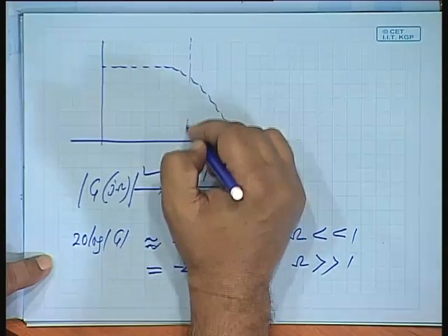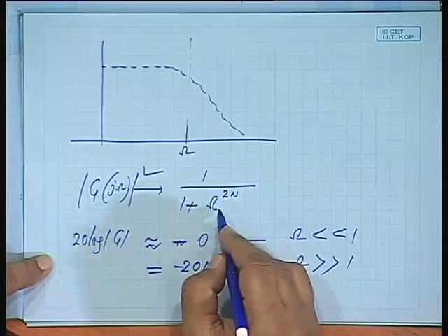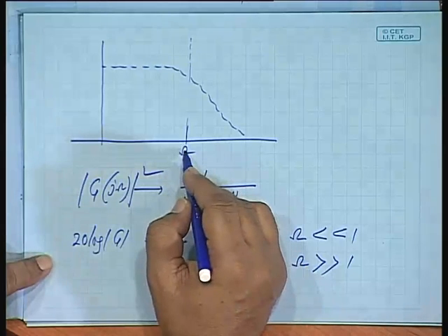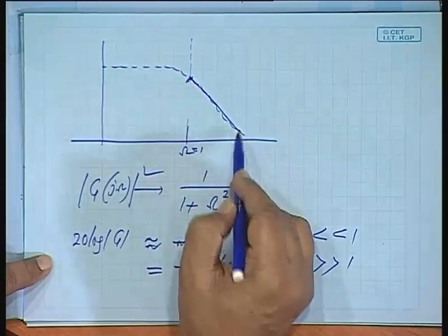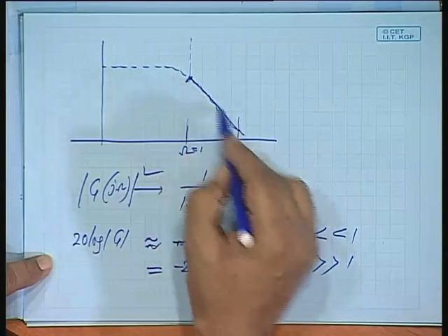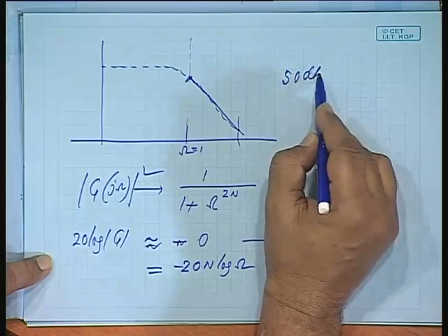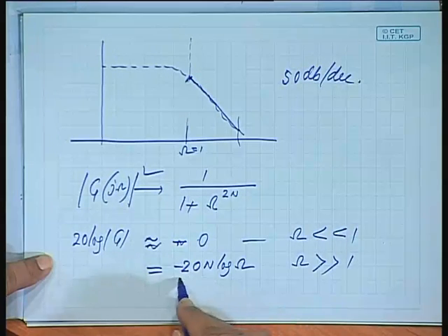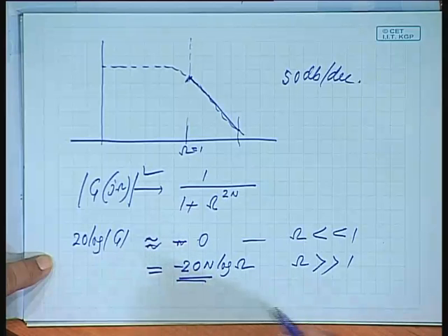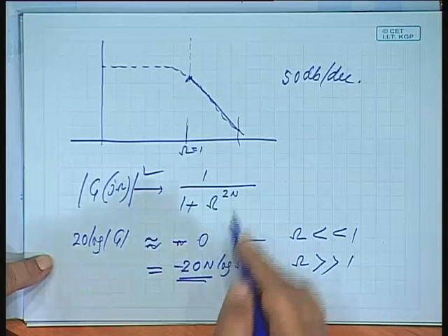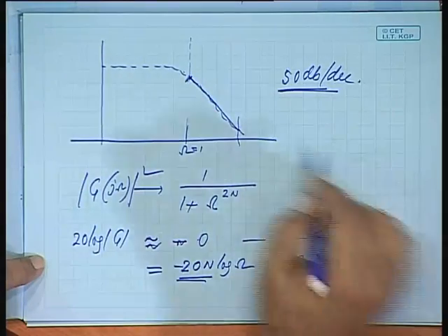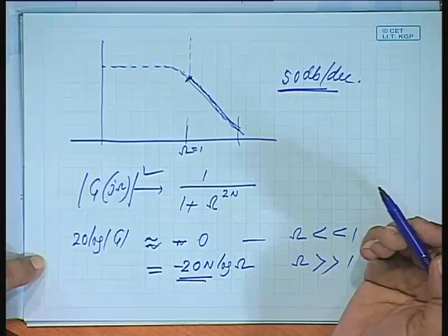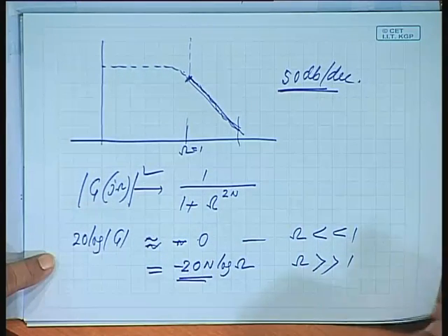And in the case of a Butterworth filter, this is normalized, that is, whatever the cutoff frequency is that we are considering. So if the rate of fall is given approximately, suppose the rate of fall is very close to say 50 dB per decade, that should match with 20 n. So what is the integral value of n closest to this? It will be 3. So if I choose n equal to 3, then I will get at least 50 dB per decade, the rate may be higher. So that is how you choose the order n in the case of a Butterworth filter.